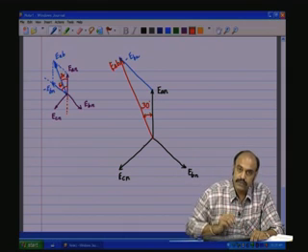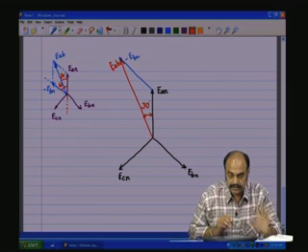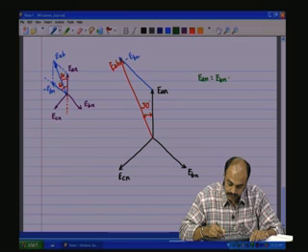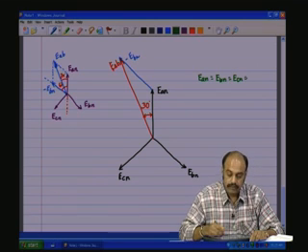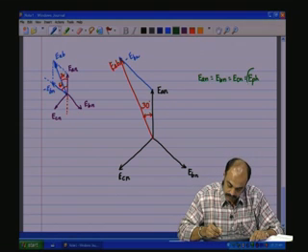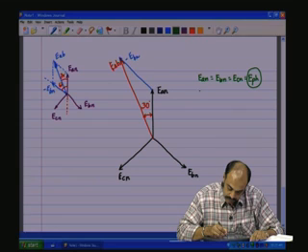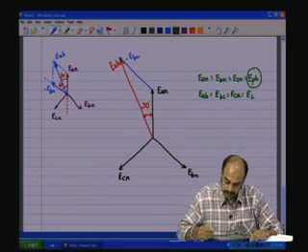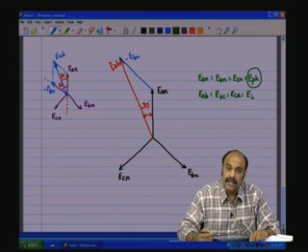Now, we said that the amplitudes of all the phase voltages effective values are the same. So, therefore, let us say EAN amplitude is equal to EBN amplitude is equal to ECN amplitude, which we shall call E phase. Likewise, EAB amplitude will be equal to EBC amplitude will be equal to ECA amplitude. We will call this E line. So, EL is the line voltage.